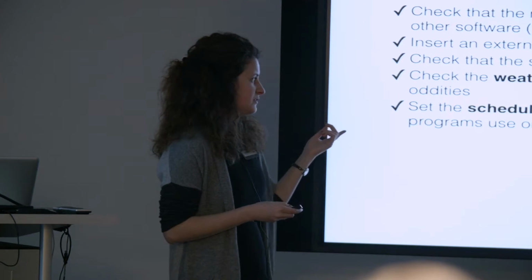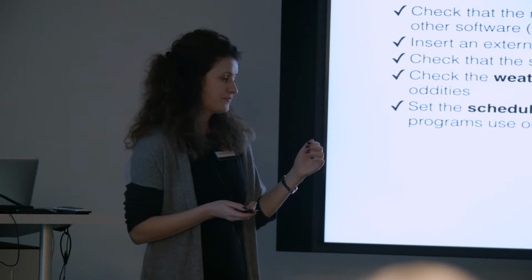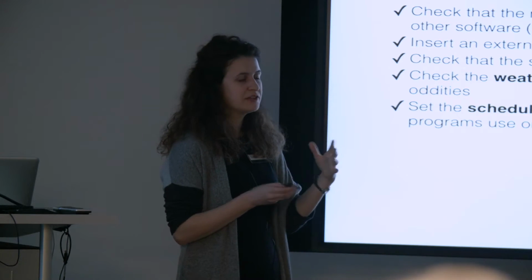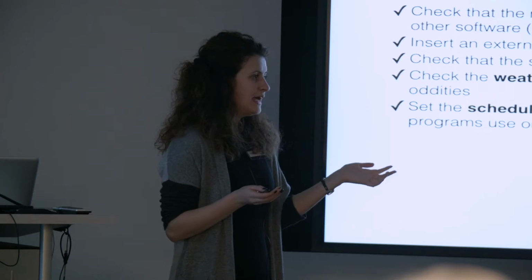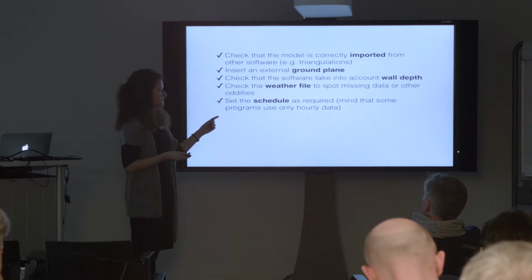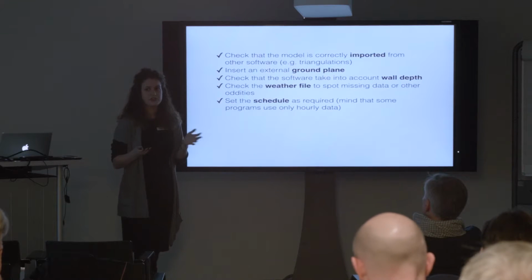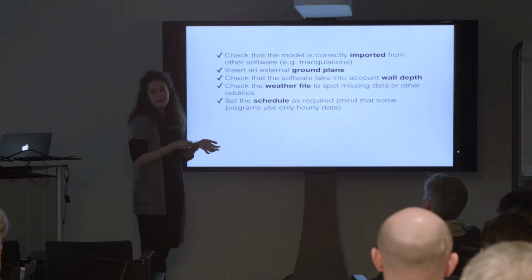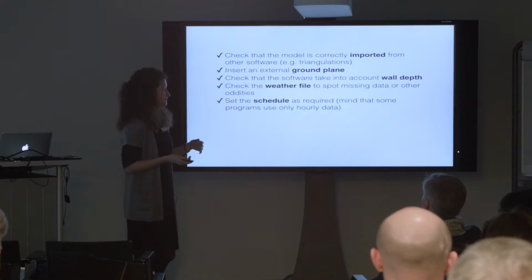Then if you have a schedule, especially for the matrix calculation, you should check that too, that the total number of hours in a year that you're taking into account is the exact one. Even more so if you are required to calculate sub-hourly data. If your schedule is starting at 8:30, you should calculate with a 30-minute time step, and some software don't do that. They have only an hourly time step, for example.